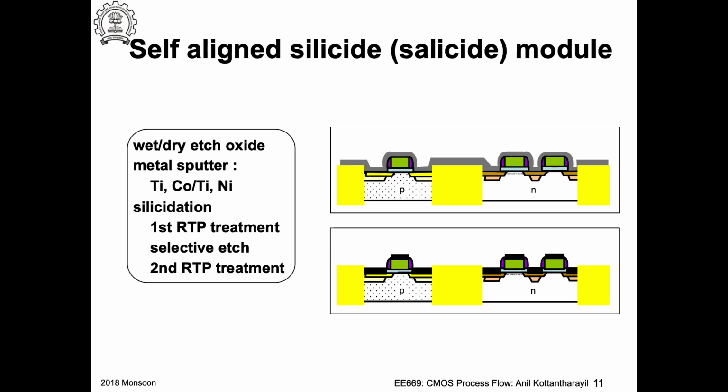Now you're going to bring in dirty stuff onto this wafer, for example copper and so on, which would diffuse very fast into silicon. So typically in a manufacturing line, the front end of line process is done in one part of the manufacturing line, and that's physically segregated from the back end of line process.